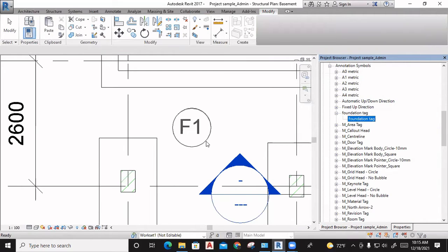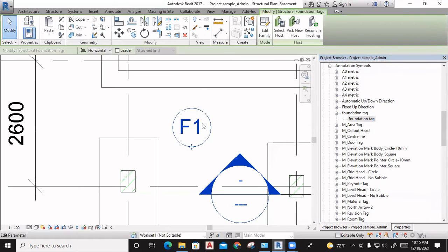So in Revit, in case sometimes it is not working, you change the way you work. Okay, instant parameter is not working for the tag. That's why I'm selecting type parameter. Understood our concept? 2D tag, 3D tag. The reference plane, the equality constraint, adding a dimension and making it as label, making a type parameter, instant parameter. That's what you should understand.